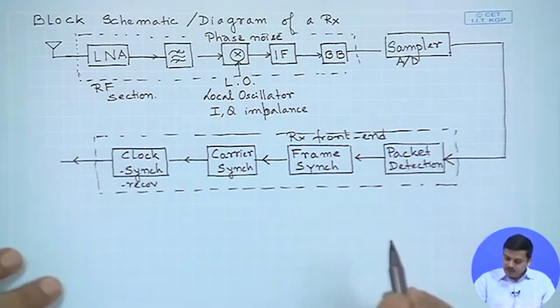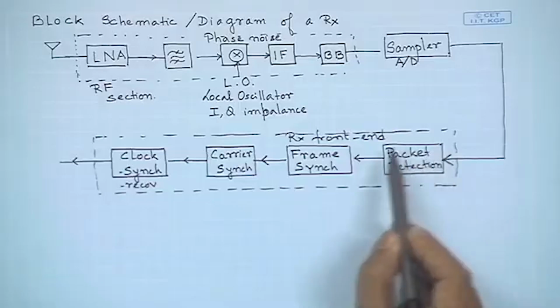Packet detection, because in digital communication systems you may encounter transmission in frames or you may encounter in packets. One particular example is the Wi-Fi, which you commonly use, where there is burst mode of transmission. So suddenly there is a packet and suddenly there is nothing transmitted, whereas the receiver should be constantly awake and should be listening to the transmissions. Now while it is awake, it is not a good idea to make the entire receiver operation on. It can simply keep the detection part on, which would set up an alert that yes, a packet is being received. So once that alert comes, the rest of the receiver can wake up, right? So this is going to reduce the energy consumption or the power consumption of the system. So there are different methodologies. So that's why we can have a packet detection in the beginning.